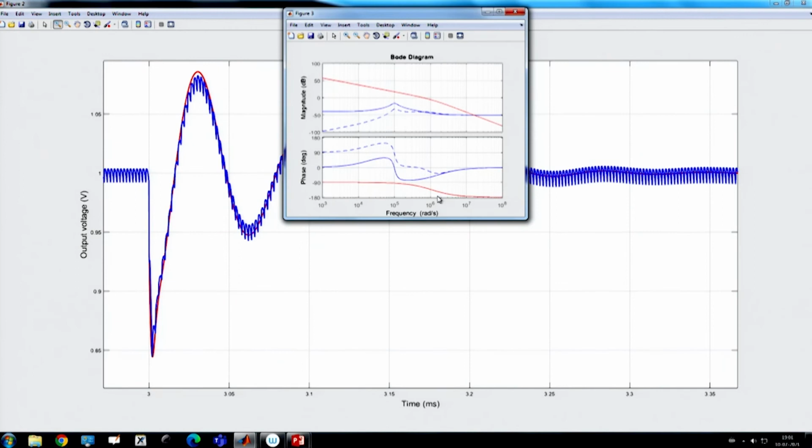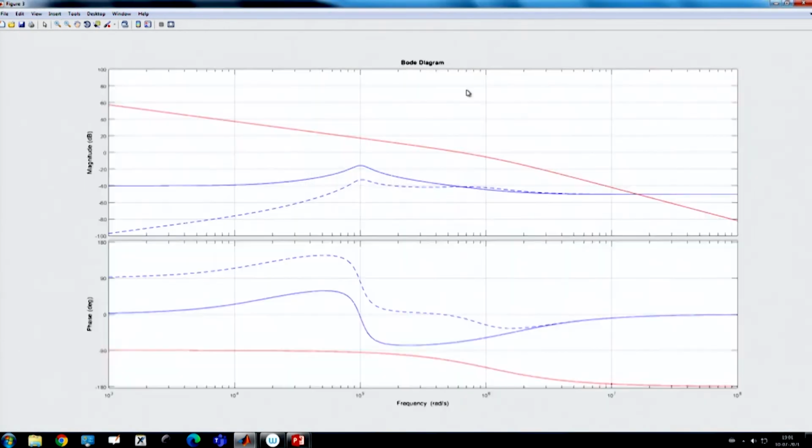That means, essentially, what we are trying to do by shifting up the loop gain, by increasing the loop gain, because we are trying to increase the crossover frequency, is reduce this peaking effect. The closed loop output impedance is the open loop output impedance divided by 1 plus the loop gain, so high loop gain around this peaking frequency can reduce the impact. But this is not a solution, because we cannot set the loop gain to be very high.